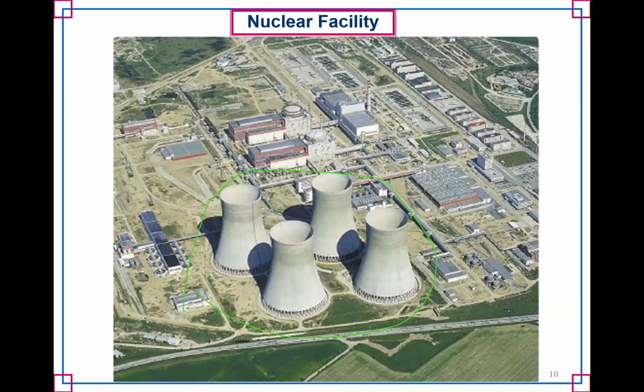Those are cooling towers. They are natural circulation cooling towers. Those are older designs, meaning they basically act like a chimney. You would spray water down here on the bottom, and you get a drafting effect that would pull air into these cooling towers. As the water is sprayed in, it is getting cooled by the ambient air, and so the hot air leaves. This is basically part of the condensing process. So you can have these.